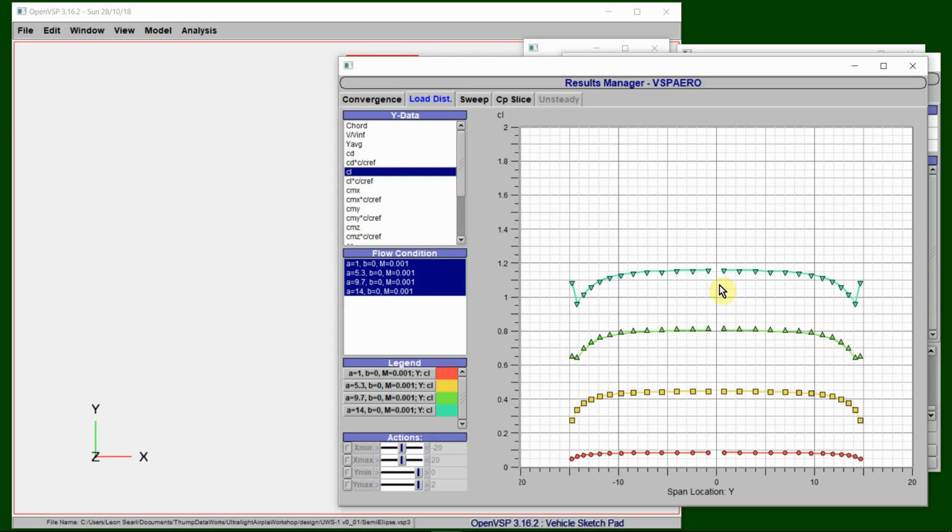If at some point here in the future, as I'm still doing design on the airplane, I start getting uncomfortable with this flat coefficient of lift across here, I'll just add a little bit of twist to the wing, and that'll bring this down a little more and get me closer to a rectangular wing performance. But so far I like this. I think we're going to go with it.